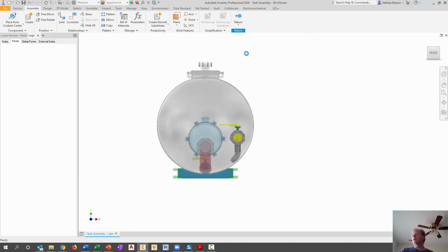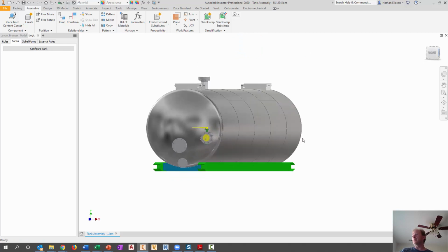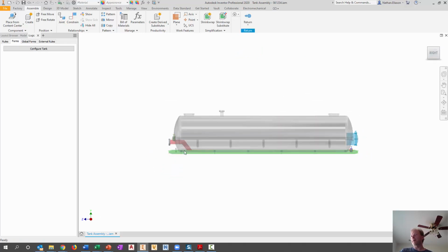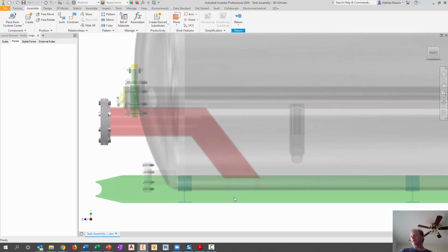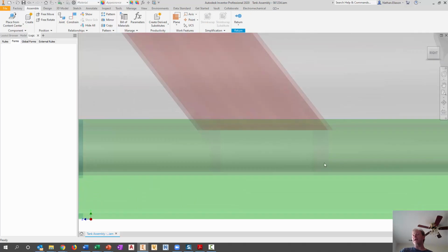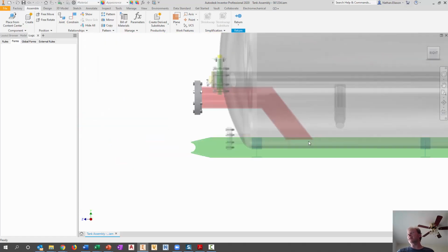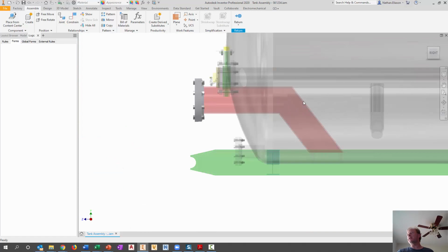You can also, if we look at our sump assembly, you can see we built it so that it has a bracket right here that rests on the bottom of our tank at the center line of the tank. And we have our pipe offset, and it knows exactly how long it needs to be so that our pipe comes out with the 20 inches height from the bottom. And we took it 15 inches from here all the way out.